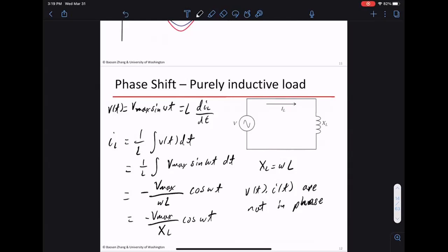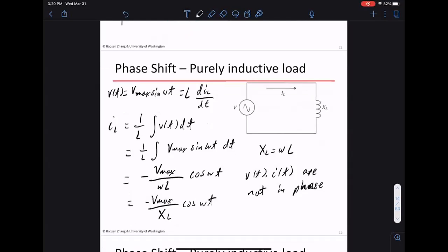So the thing to remember is that the inductance shows up as XL, the reactance of the inductor. If you take an inductor in the US grid and now you move this inductor to Europe, a 50 Hertz grid, you suddenly have a smaller inductor. So this XL is actually a frequency dependent value. In the US we have 60 Hertz, so that's omega. But in Europe we have 50 Hertz, so it's a smaller XL. That's something to remember.